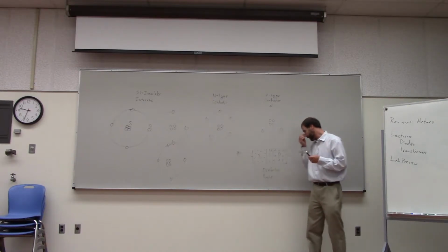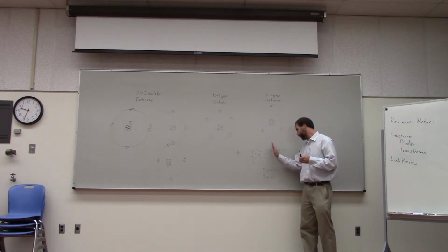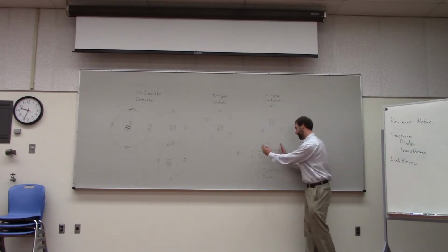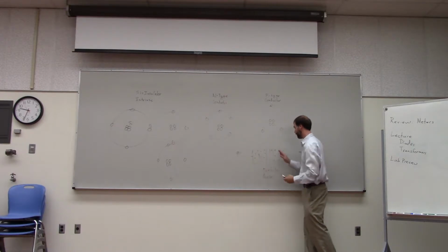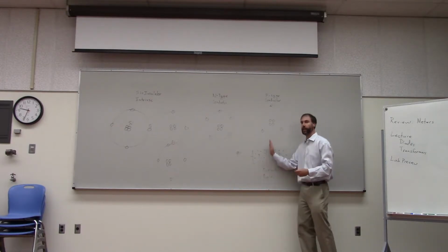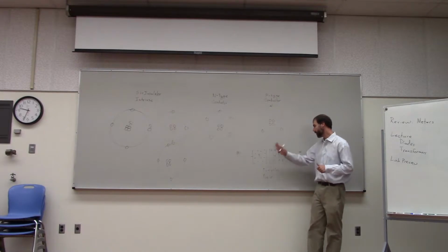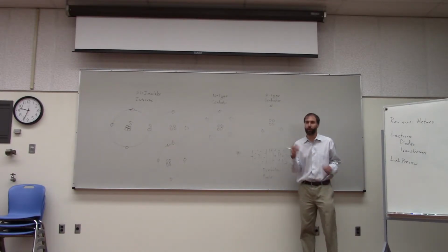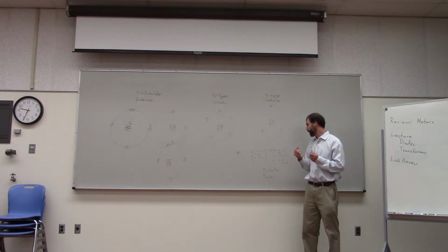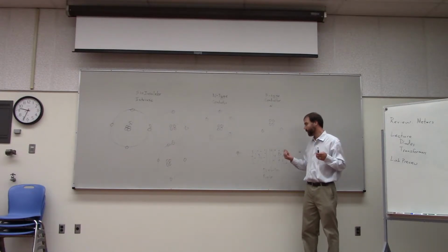It is similar to a capacitor because you have these two areas that have charge on them and they're separated by an insulating layer. So diodes have some capacitance to them. In fact, there are certain diodes that are specifically designed to work with their capacitance.